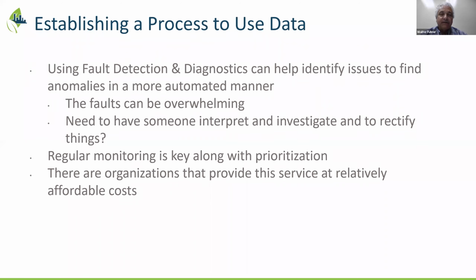And one of the things in fault detection that has been coming forward is what's known as people counting, as opposed to, say, monitoring CO2 and volatile particulate in a room. You have a meeting, and now the ppm has hit that 1,000, 1,200 level, and now the VFD HVAC goes into full mode. Well, all of a sudden the meeting's empty and there's no one in the room anymore. So it kind of defeats that purpose.